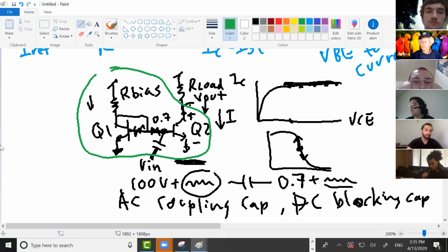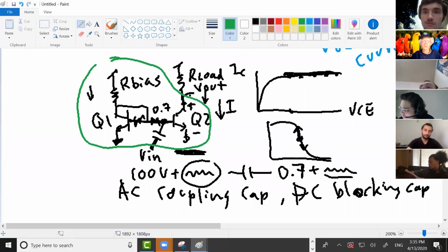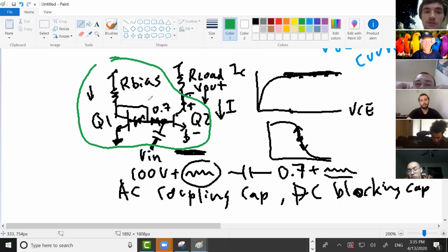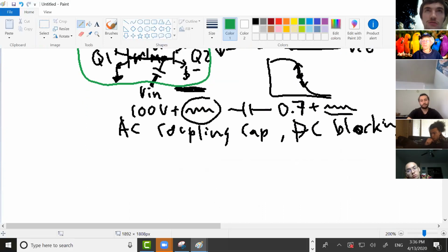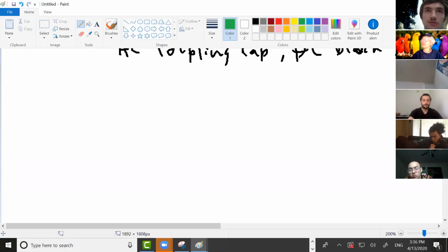Right, so let's do one more step here. Again, what hurts circuits? Current. All right. So in this case right here, if there was runaway current, if you accidentally set your VBE too large or something like that, this thing could fry.